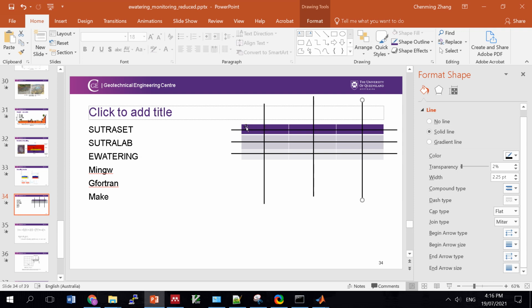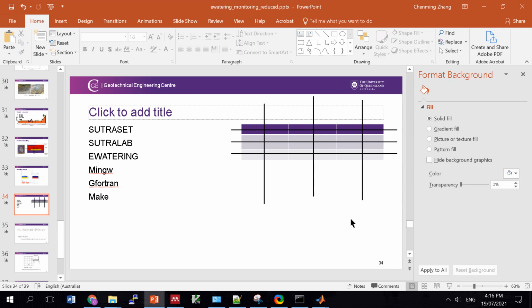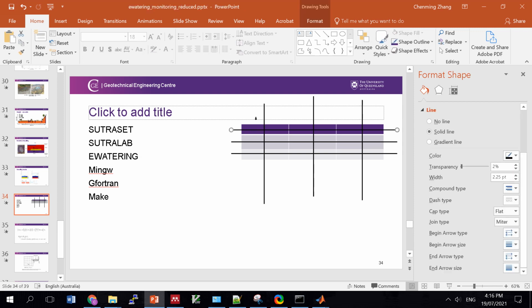So this is cell 1, cell 2, cell 3, and cell 4, and likewise you've got other cells. So the number of cells is the same as the number of nodes. But the difference is that when you've got a cell, you've got a finite volume, but you don't have a volume when you're talking about a node. The element has volume as well, but an element is an add-up of several cells, as you can see here.